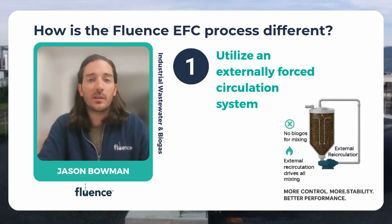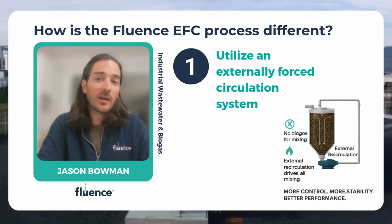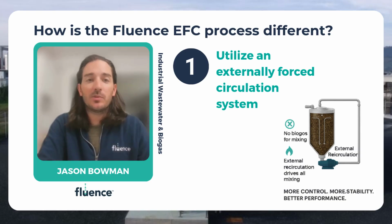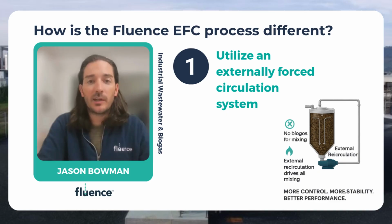This is really to make a claim that you use less external mechanical energy by borrowing some of that biogas. We actually aim to decouple our reactor mixing from the biogas production because it allows us to mix independent of the biogas output. So this is a huge advantage for maintaining process stability and maintaining granular retention.